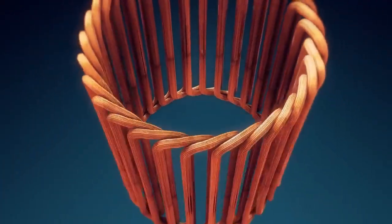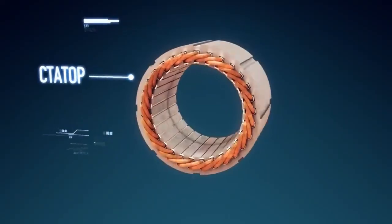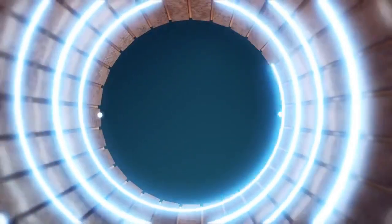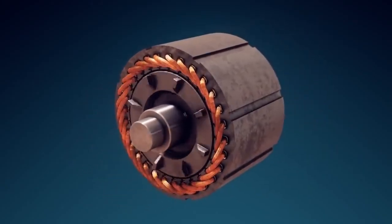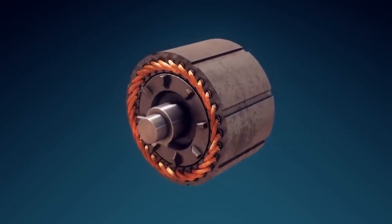So, what is the advantage of the three-phase system over others? 3 phases is the minimum number of phases required to create a stable rotating magnetic field, which can reliably start a motor and keep it running. The three-phase system is stable, balanced, and provides a high-quality rotating magnetic field. At the same time, it uses the minimum number of wires to transmit energy.